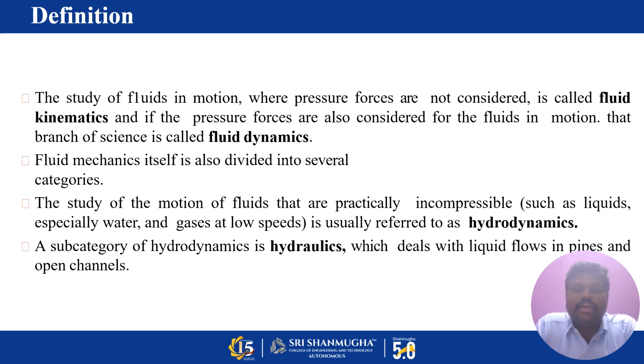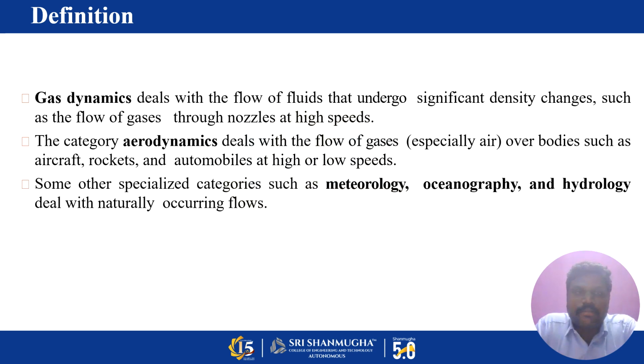A subcategory of hydrodynamics is hydraulics, that deals with a liquid flowing in pipelines or open channels, for example rivers, streams or channels. Gas dynamics focuses on gas flowing through pipelines or nozzles at high speed. Here it is a compressible fluid, so the density will vary from place to place and point to point.